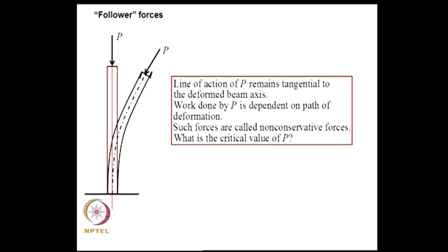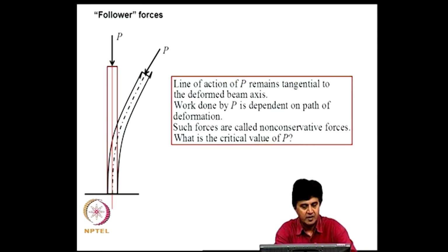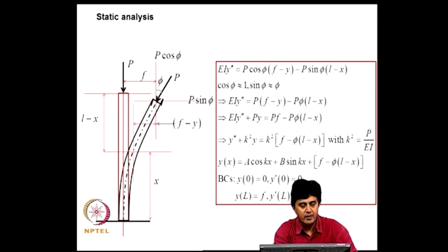Now, the next problem that I mentioned was that of so called follower force problems. Here the line of action of P remains tangential to the deformed beam axis. So, work done by P is dependent on the path of the deformation. Such forces are called non-conservative forces. So, what is the critical value of P? That is the question we are asking. What we can do is perform a static analysis.